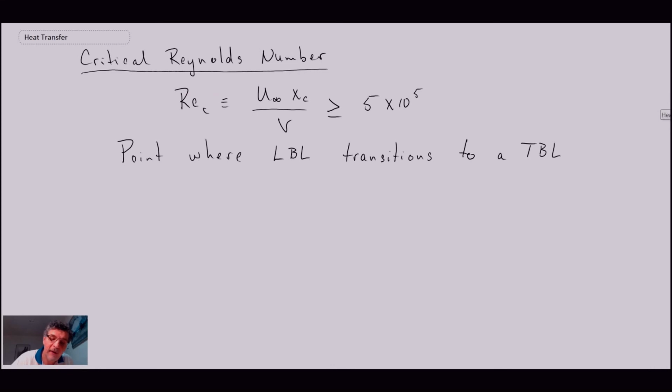Because even with a rounded object, let's say you have flow over an object like this, we can zoom in to parts of that object and treat it as being almost like a flat plate. There will be an external pressure gradient which will have an impact on the boundary layer, but at any point you can piecewise look at the flow over any kind of object in the manner of looking at it like a boundary layer, unless you get to a separation point.